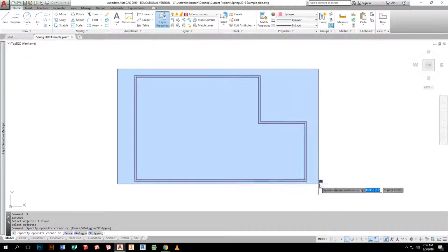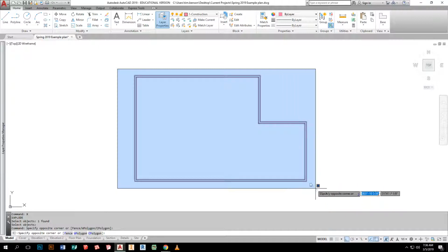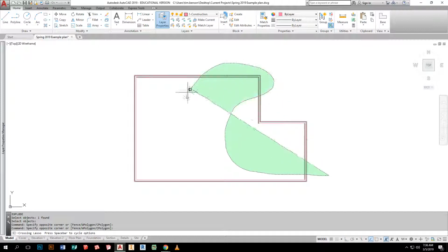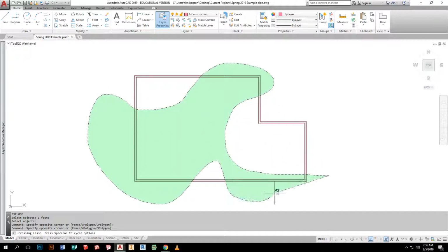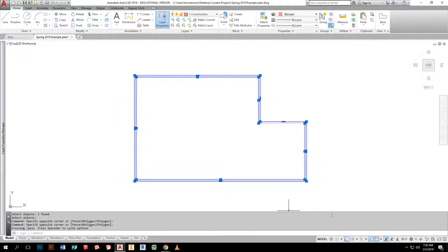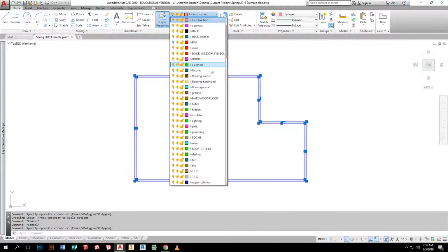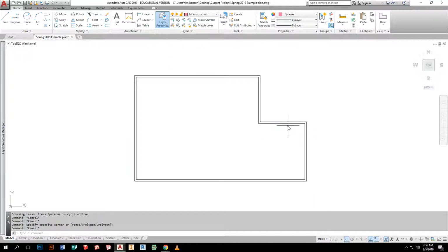Now, this is one of those things I learned old school where you only had the rectangular options. In the new version, if I click and hold my mouse wheel down, I can do this kind of stuff, which kind of drives me crazy, but whatever. But I'm just going to highlight this, go up here to my construction layer, pull it down, find my 1-walls, which will be down here because everything's alphabetical, and there's my walls on my first floor placed. It's not meant to be hard, it's actually meant to be pretty easy. Now, I'm going to do another construction line.